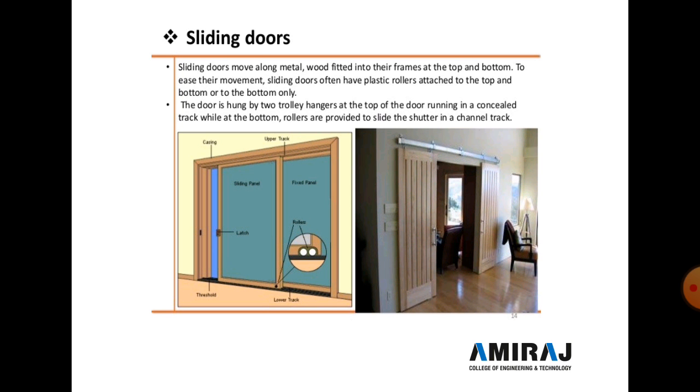So here see this figure. A sliding channel is provided. In a sliding door, see this figure number 2, the sliding door looks like a sliding window, and in a sliding window, a sliding roller is provided at the bottom, but in a sliding door, the door shutter is hung from the upper side. So here see this figure number 2. One sliding channel is provided, and from this sliding channel the door is hanging, and then